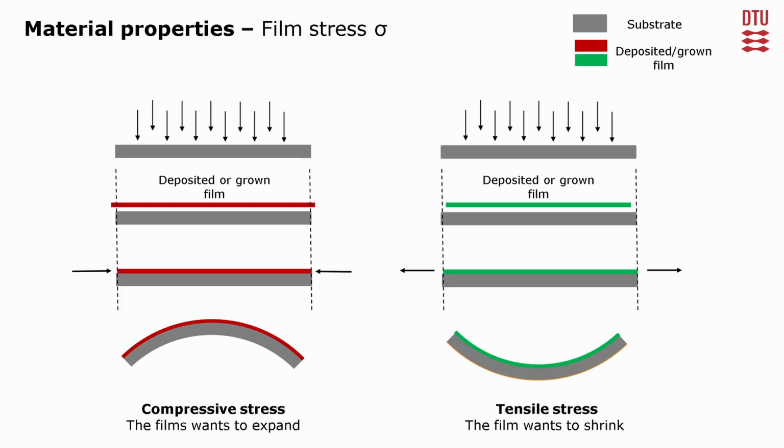Stress can cause the wafer to bow. A wafer might appear normal but fail vacuum clamping when moved to another chamber due to surface curvature.